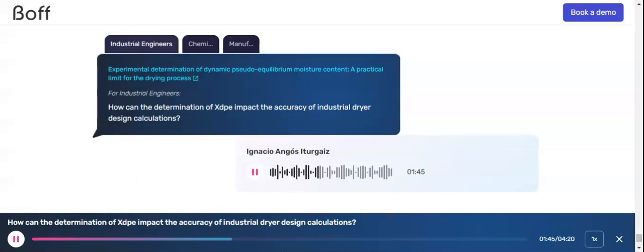The drying kinetics of a material, on the other hand, refers to the behavior of moisture decrease during drying. Drying kinetics, after being fitted to a mathematical model, is the main basis for rigorous design and simulation of industrial dryers.